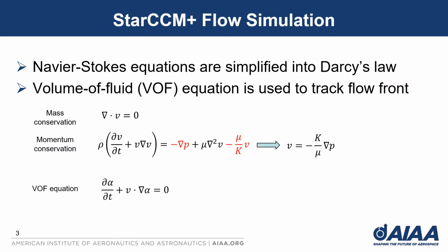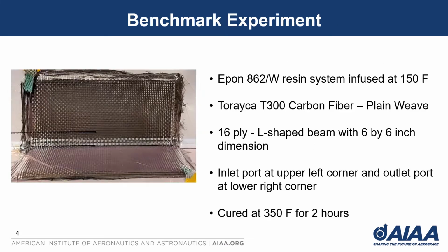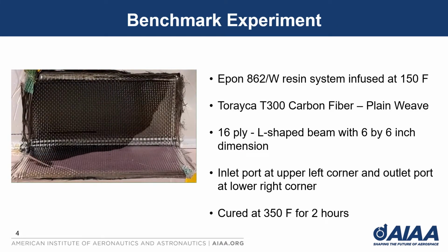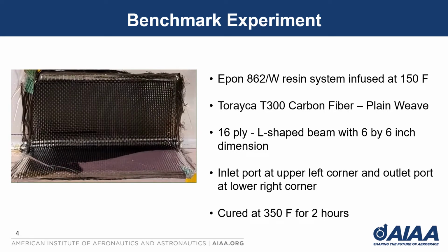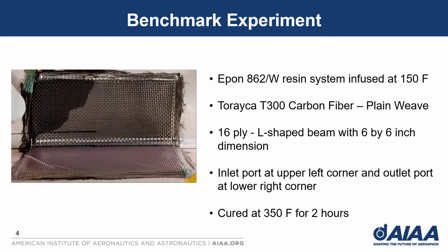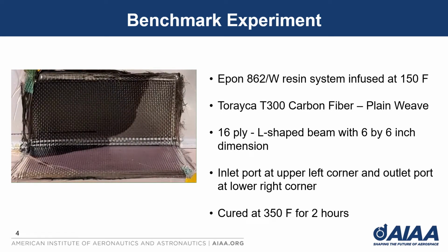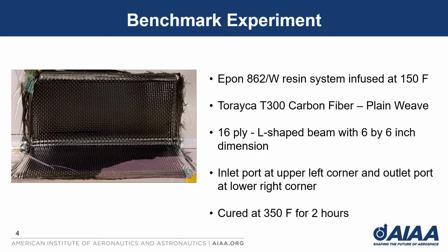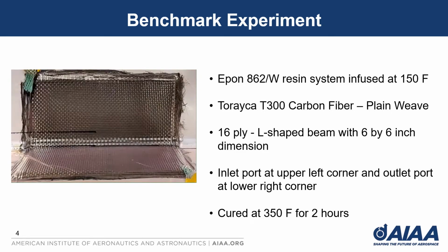So in STAR-CCM flow simulation, we solve the Navier-Stokes equation, which essentially reduces to Darcy's law in liquid composite molding. The volume of fluid method is used to capture the flow front. We first carried out a benchmark experiment for the purpose of model validation. It is an L-shaped beam structure using vacuum-assisted resin transfer molding. Resin is injected from the upper left corner and vents out from the lower right corner. After infusion, the resin is cured at 350 Fahrenheit for 2 hours.